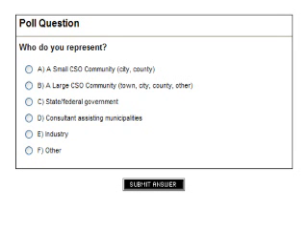So my question is, as good engineering practice, don't you think it would be wise to consider any kind of leakage from the tunnel? Well, you really don't want to have leakage from the tunnel. Yes, to go into the groundwater. So in that, you would. That was the answer I was expecting from you, that you need to make sure you are not leaking to the groundwater when you're storing that dirty water inside the tunnel. Correct. Thanks a lot.